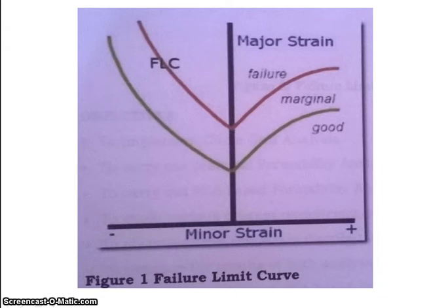the sheet. The forming limit diagram shows the metal formability at less cost. It typically represents the maximum permissible range of major and minor strains that a typical sheet material can undertake without failure. Practical formability analysis is represented by the FLC or FLD. A forming limit diagram is a graphical representation of the stretching capability of the material. The stretching limits are a function of the major and minor strain.